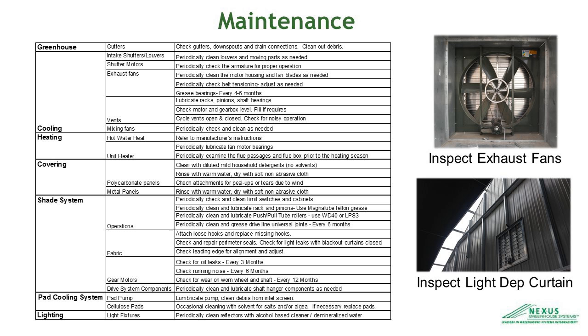And so before you start it back up in the summer or in the spring, just check it over, make sure the pump's clean, take out any debris. On occasion, you could replace the cellulose pads. More often than not, folks will put an algicide or some kind of sanitizer solvent inside their reservoir to clean the pads and get extra use out of them.